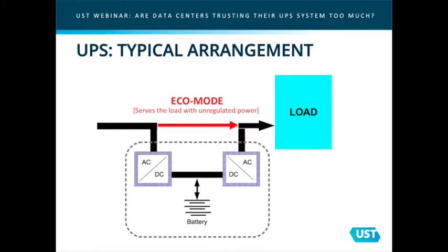What we discovered, though, is that most people who have purchased this don't implement this technology just because it might be difficult to tune. When does the UPS turn on? When does the UPS turn off? Different voltage characteristics based on site conditions. So what we generally found was that while this seems like an attractive marketing concept by promoting greater efficiency, it isn't very well accepted in reality in the marketplace.